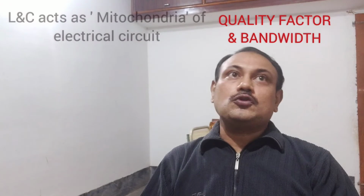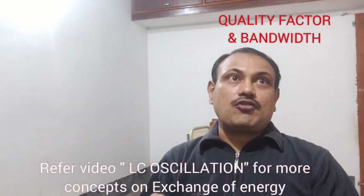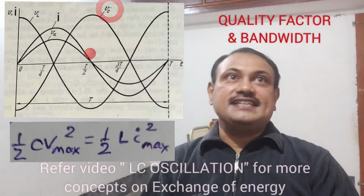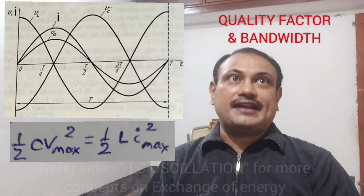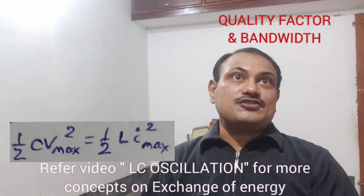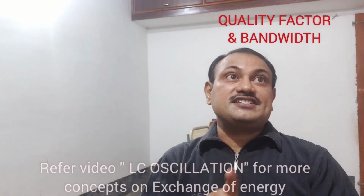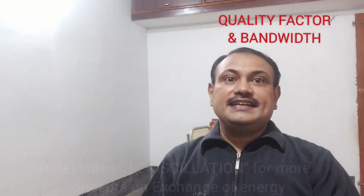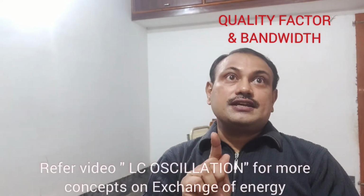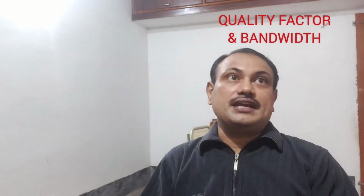Coming to the quality factor and bandwidth of the LCR series circuit, at resonance a constant amount of energy is stored by inductors and capacitors. That is, when the capacitive voltage drop is maximum, the inductor current is minimum, and vice versa. Hence you can write half C V max square equal to half L I max square. And recalling the voltage resonance property of the LCR circuit, the resistor of an LCR series circuit is usually low compared to the values of L and C. Hence the potential drops across the inductor and capacitor are considerably high compared to the source EMF.